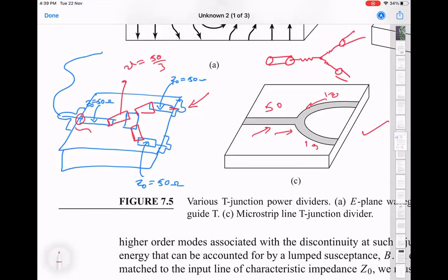This length of transmission line is completely irrelevant, because all the way from here down to wherever this cable is, everything is 50 ohms. So it's just moving some reference plane. The active part of the device is really what is contained here. It's really just 3 resistors of 50 by 3 value, all connected at one point and connected to the center conductor of your transmission line. Right? There is no connection to the ground on this side. The ground is anyway common for the microstrip.